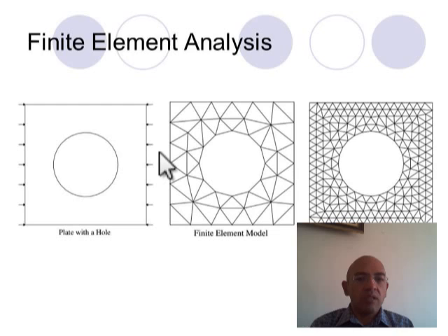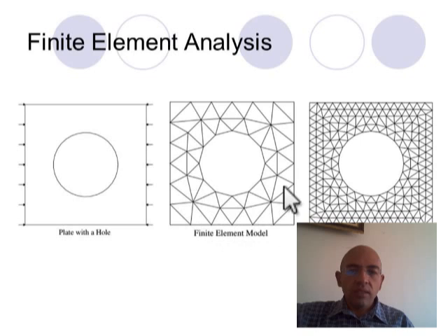We have seen how we use numerical methods for solving some mathematical problems. Now in finite elements, the first thing is we divide the domain of interest into subdomains. This is the first step. You may divide one edge into 10, or maybe 40, 50, so it depends. At each node, we are going to see it in detail, we have some unknowns and we generate a set of linear equations at the end, and then we solve these sets of linear equations. Within this course we are going to see how we do it.